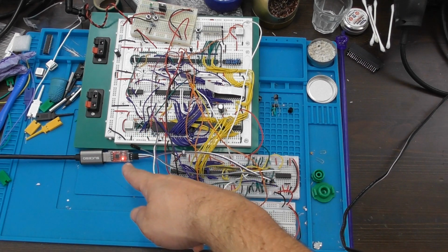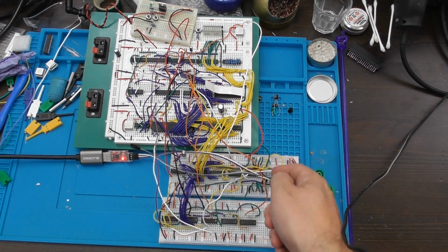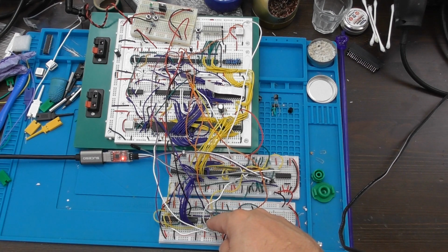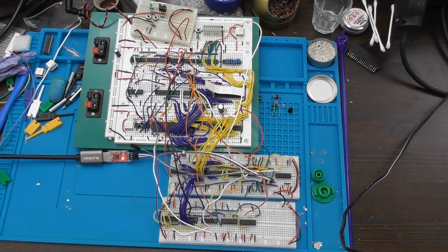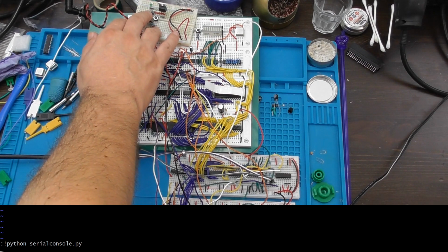Our code's not using that yet, but it should be working fine. And I've connected the transmit pin from the FTDI through to the resistor network here, and that goes back to the received data signal on the serial circuit. So otherwise this is the circuit which was in the schematic with the corrections I already mentioned, and we have the terminal on screen so you can see what's going on. Let's turn it on and see what happens.